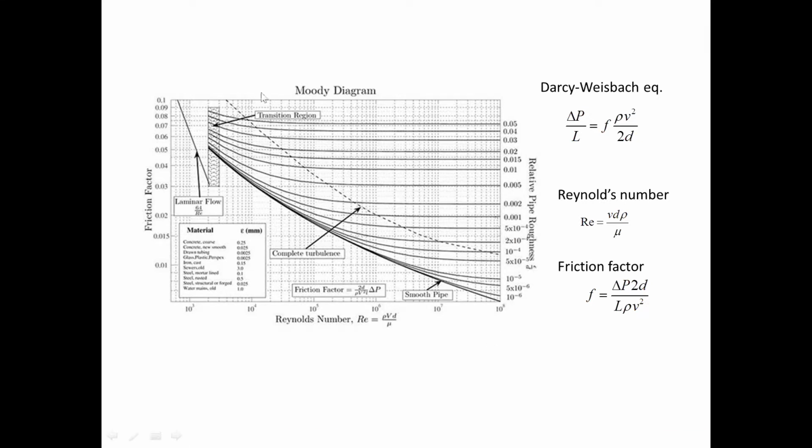So what I want to do is use this analysis of friction as a function of Reynolds number to verify the analysis of flow in a circular tube. We'll go through the analysis and calculate the Reynolds number using this equation, and calculate the friction factor using basically the Darcy-Weisbach equation where we've solved for the friction factor. One thing I should point out is this term here, dP, the pressure drop, the difference in the pressure over this length. So when we do the verification, we'll have to calculate that. So let's go over to Comsol.